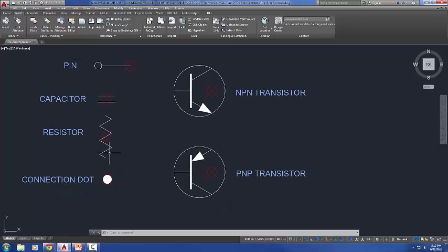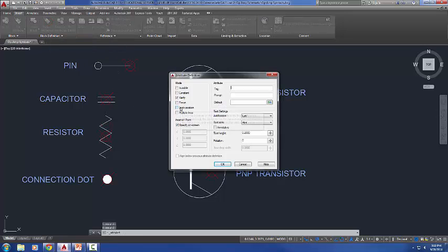In order to do it, you cannot choose from this list. You'll have to go to Manage Layer States. While you're in this Layer States Manager, you'll select First Floor, and then you'll say Restore. So I show my first floor here. That looks good. I'll come over here, go back to my Layer States Manager. I'll say second floor, restore.